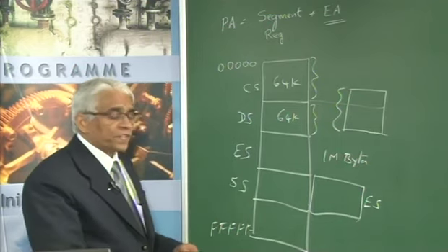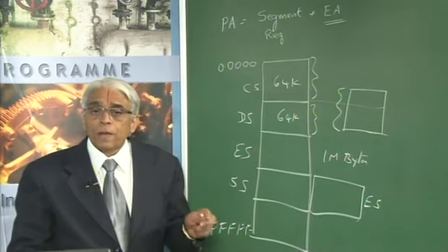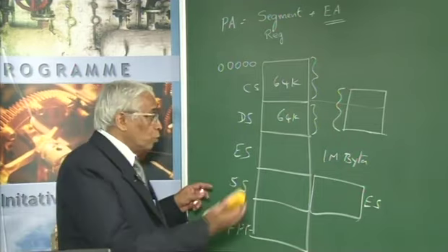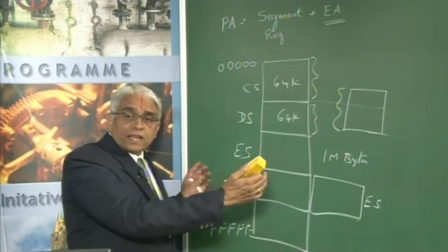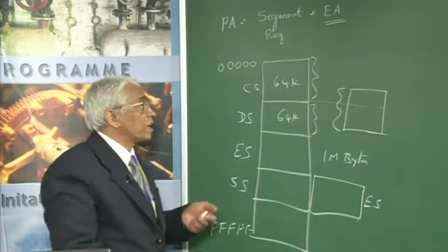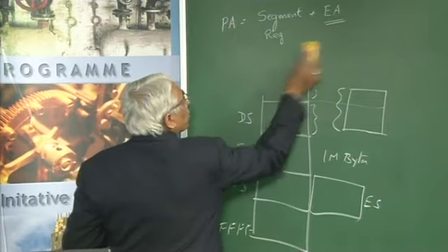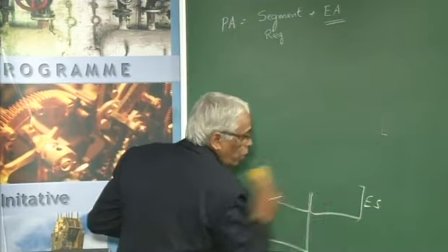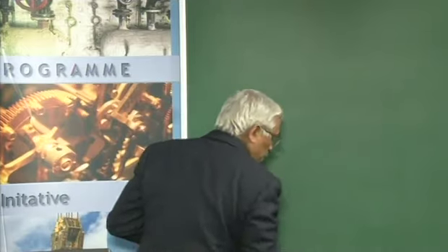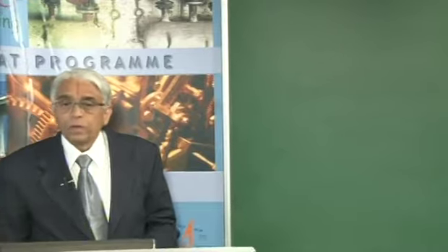This causes a certain type of problem. If you use one segment and write to it, and then using another segment write onto the same location, it destroys the contents of the memory. So, this is not a very good practice, initializing all the segments with the same address.